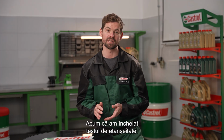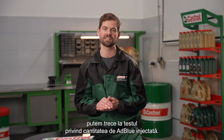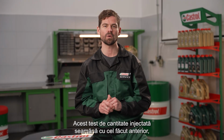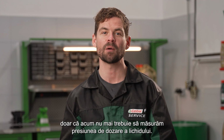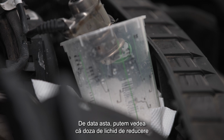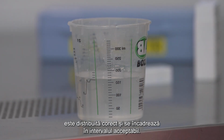Now that we've concluded the leak test, we can move on to the AdBlue injected quantity test. This is where we can confirm that replacing the dosing valve has resolved the issue. This injected quantity test is similar to the one we did earlier, except that this time we no longer need to measure the fluid dosing pressure. This time, we can see that the amount of reducing fluid is dispensed correctly and well within the acceptable range.